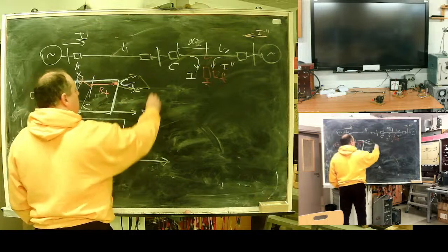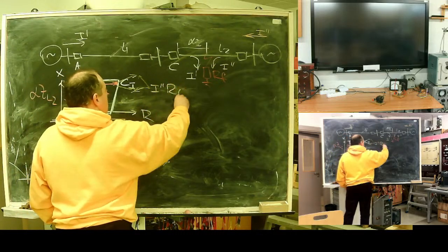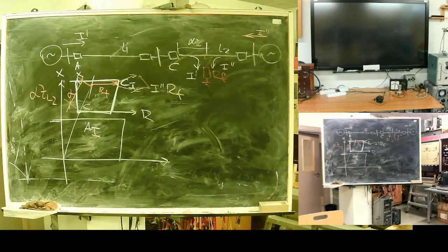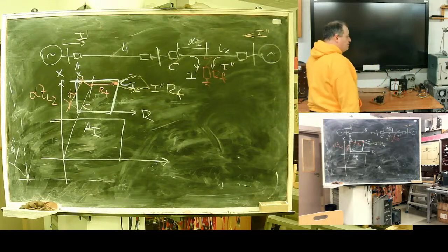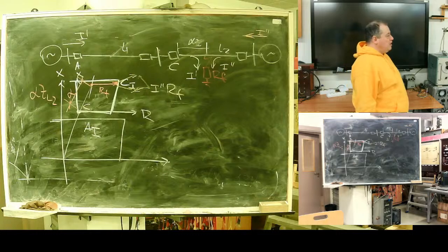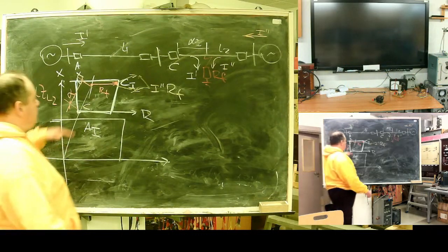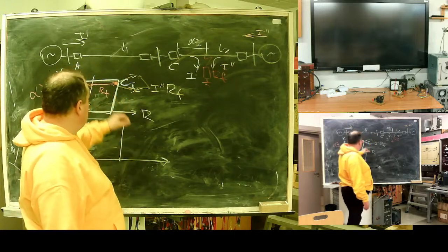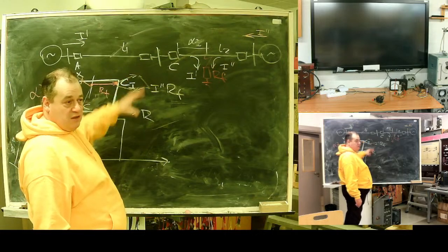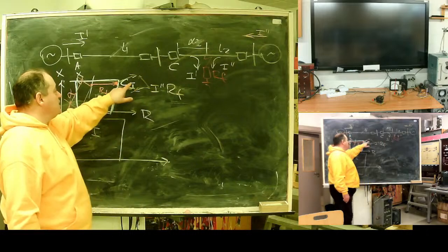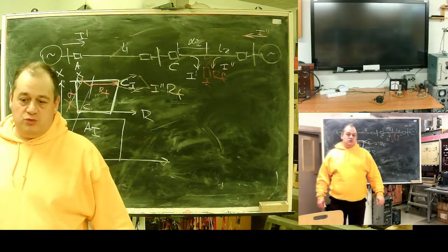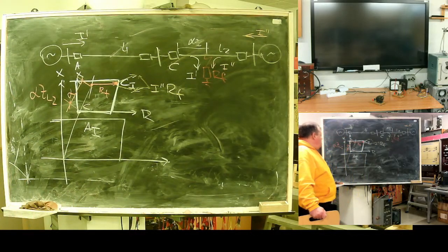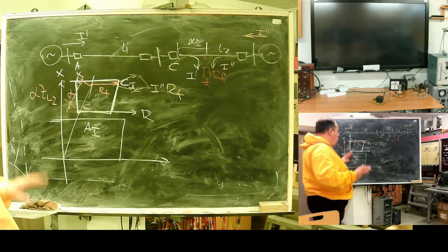These two I can predict. It's a result of I2 multiplied by RF. Additional resistance. If there is no angle shift between systems, we had no power transit before the fault, I can predict it will go straight. But the higher the transit between systems before the fault, the higher will be the virtual negative resistance. Current from the second system introduces a kind of virtual reactive resistance to the fault place. It adds it.